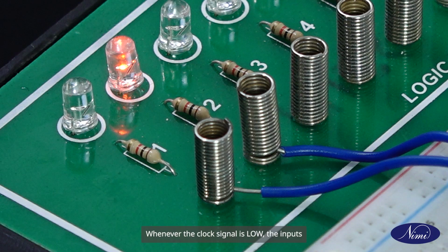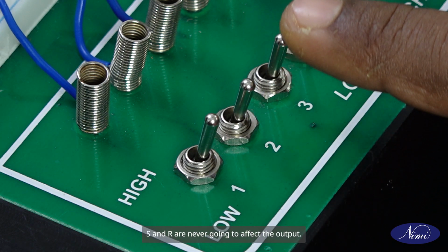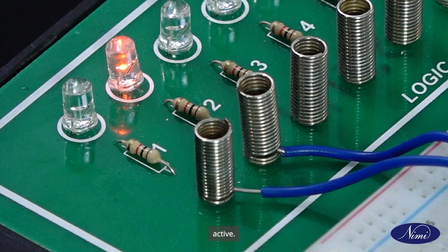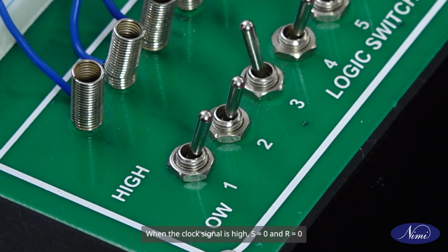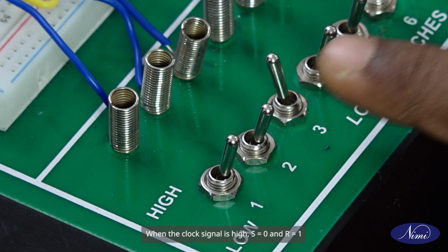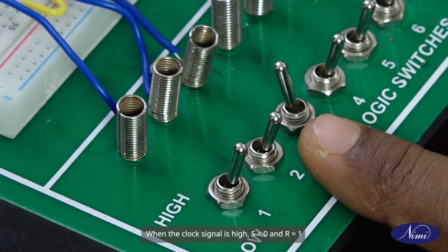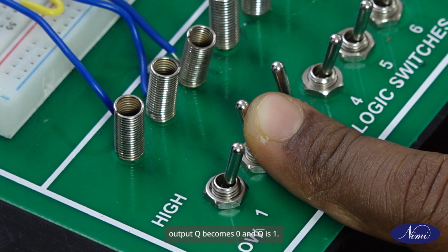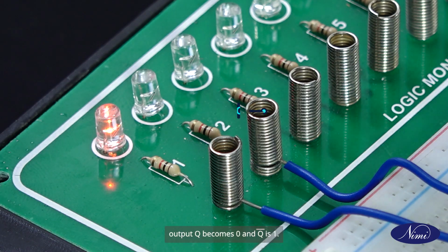Whenever the clock signal is low, the inputs S and R are never going to affect the output. The clock must be high for the inputs to be active. When the clock signal is high, S is equal to 0 and R is equal to 0, output Q and Q bar remain in their previous states. When the clock signal is high, S is equal to 0 and R is equal to 1, output Q becomes 0 and Q bar is 1.